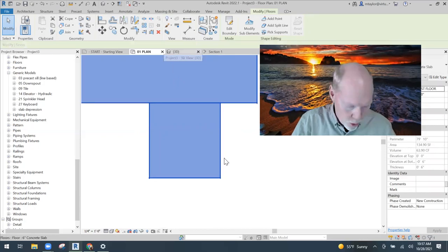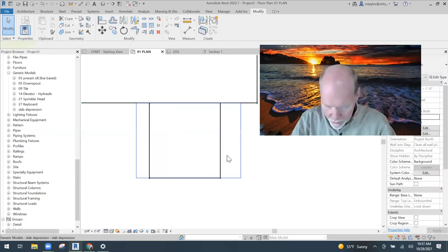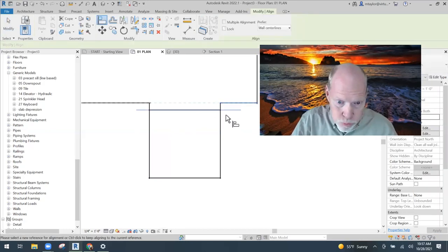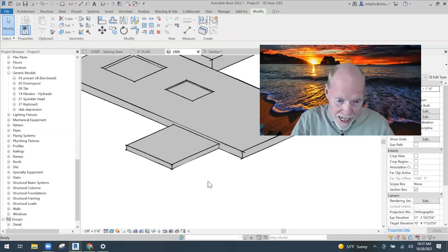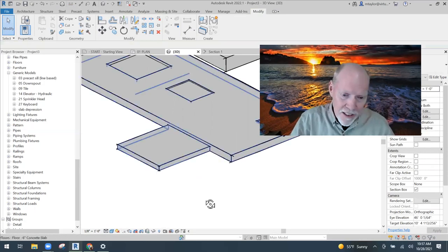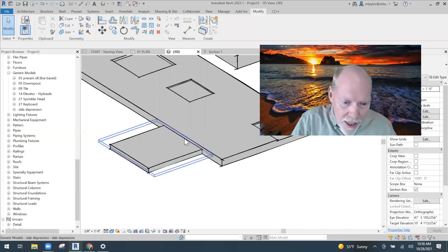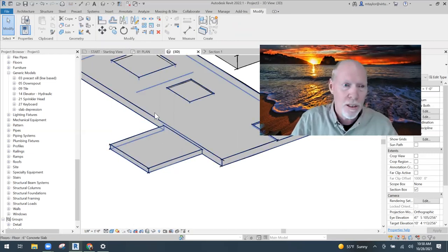So let's go to, I'm just trying to, there she is. Okay. So I can align it. I'm going to align this guy to the slab edge exactly. And so it is cutting down 2 inches here. Okay. And so we've got a slab that extends. Now, could I have put a separate slab out there? Yes. But I'm just showing you that this thing, this little guy that we made, can be placed on any extension to make it thinner and depressed at that area.